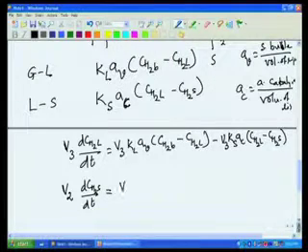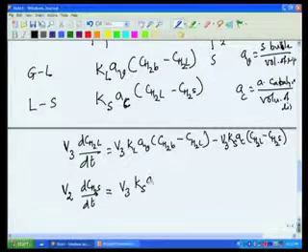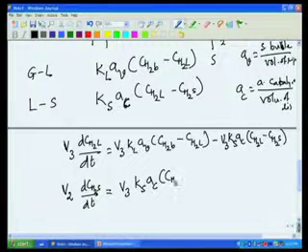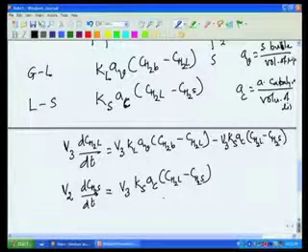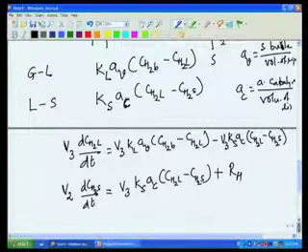This must be the rate at which hydrogen from the bulk liquid is coming to the surface, plus the rate at which hydrogen is getting generated at the surface. This must equal the rate at which hydrogen is getting accumulated. Now, I am expressing my rates in terms of volume of the bulk liquid.